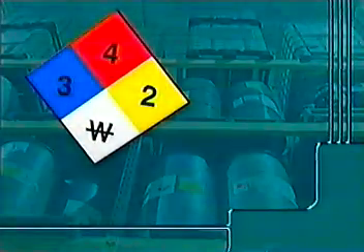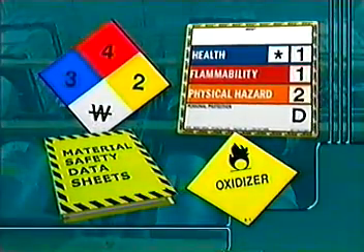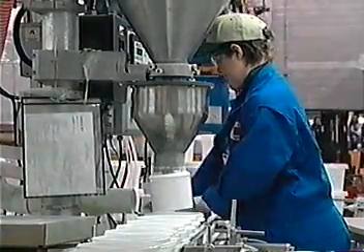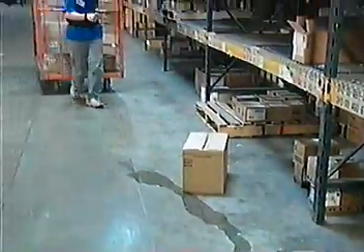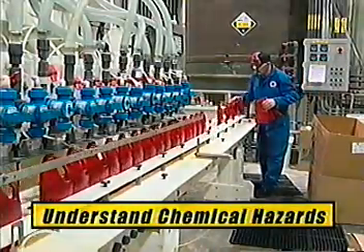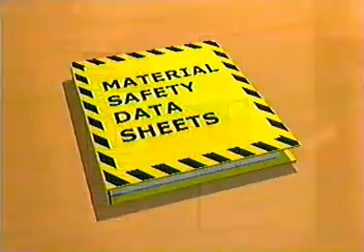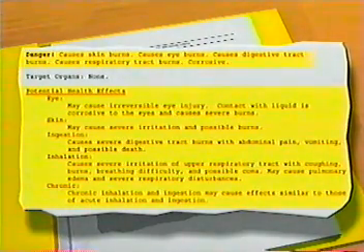Hazard communication involves the use of container labels and material safety data sheets to provide you with information on a chemical's potential hazards. Before using any chemical, use these sources of information to understand that chemical's health hazards, safety precautions to take while handling it, and procedures to follow in case of an accident. First, understand a chemical's potential hazards. This information is readily and easily available from the container labels on the chemicals themselves. The Hazards Identification section of the MSDS will list more detailed information on these hazards, including the symptoms to watch out for if you or your coworkers have been exposed to the hazardous chemical.